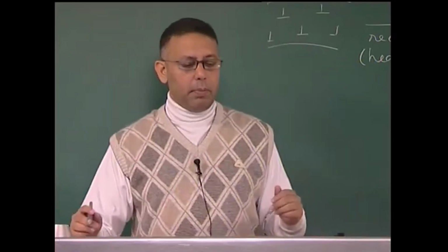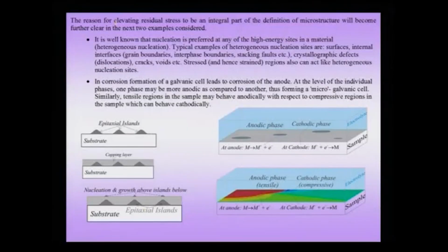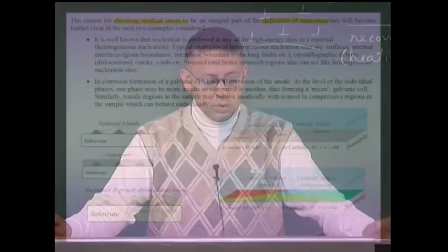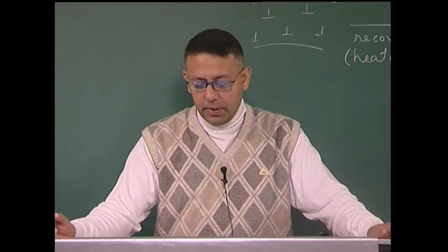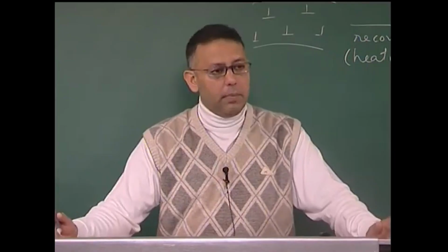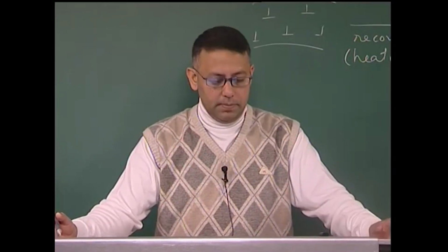We will consider a few more examples to see why we need to elevate residual stress to be an integral part of the definition of a microstructure. In these two examples, the first I consider is the nucleation and growth of epitaxial islands, and the second is the presence of precipitate phases in a material.